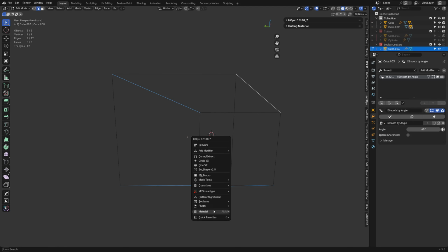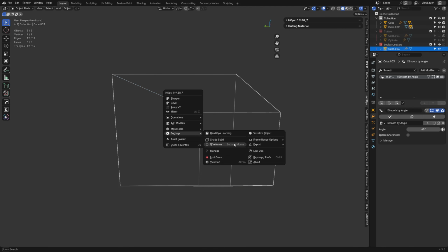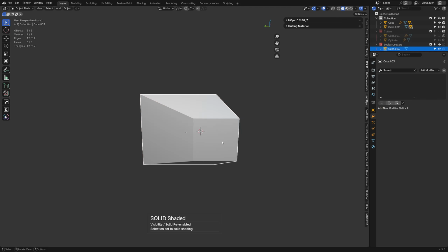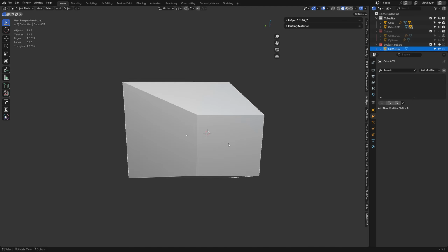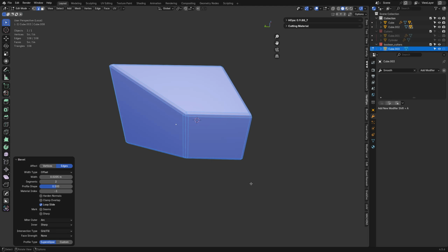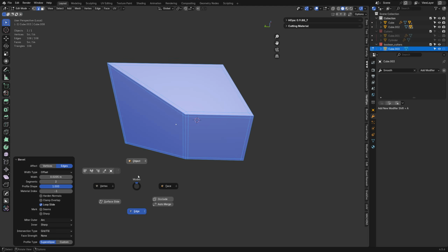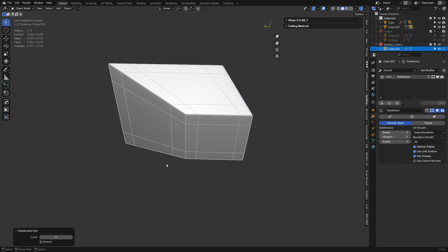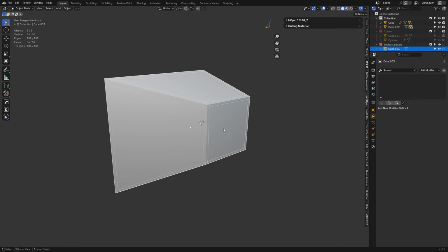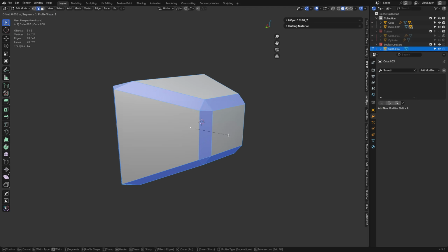Surprisingly, the answer to this is probably not what you thought it was. It's subdivision. So you're still going to create subdivision mesh. Like a lot of people are like, you don't need subdivision. Yeah, you do sometimes. And this is one of those cases where if we just beveled this like this, change the profile shape to 1, it's all quads, guys. It subdivides perfectly fine. So this is going to be more squared up like this, possibly, right? But we could bevel it differently.